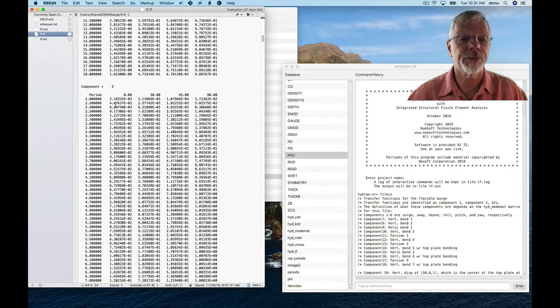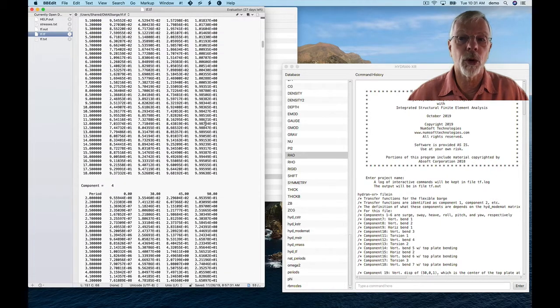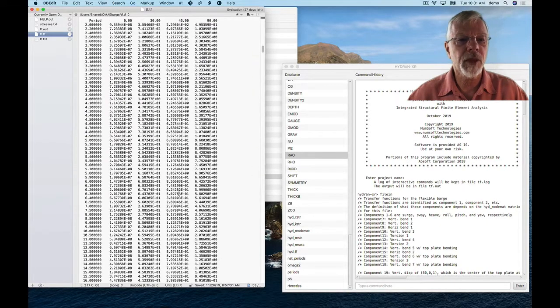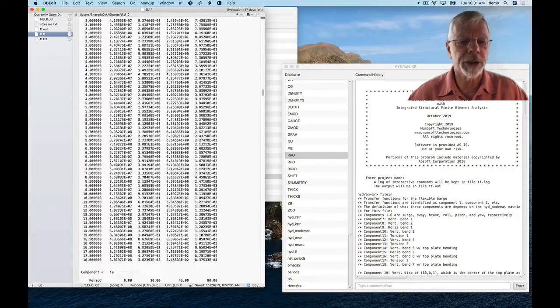Similarly, in heave, there's going to be heave in any wave direction, so we see that there are reasonable values in each wave angle. And for one other check, one should spot monitor, is that at large wave periods, long waves, the heave should approach 1, and we see that it does. So we get the RAO for each of the response quantities.